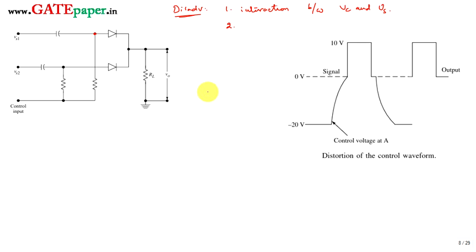Second disadvantage: even though we say the delay between output and input is very very small, because the output is coupled to the P side of the diode through a capacitor, and the capacitor doesn't change instantaneously, the changes in the input directly appear at the P side of the diode, which is the output itself during the transmission period, as the diode is forward biased.